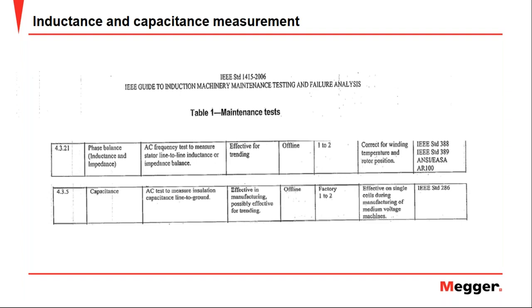If we make a single measurement of inductance and capacitance, this value doesn't indicate the insulation condition. Only through an inductance and capacitance trend can we make an accurate analysis of the motor insulation condition.